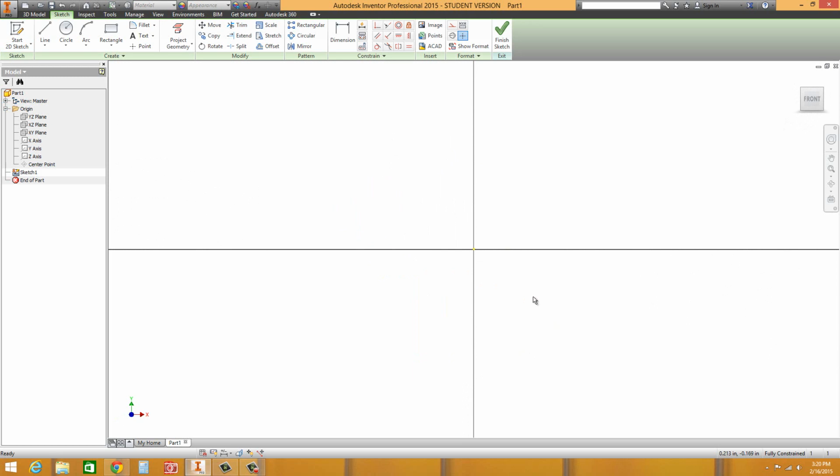Now in the center you have your little origin. Avoid accidentally deleting that if you can. Sometimes people click and drag over it and hit the delete key and then that's gone. You can reinsert it, it's just that it's easier if you just don't fiddle with it. Let that be your origin. That's your 0 marker in space, your 0 for X, Y, and Z in this case because of the plane we're drawing on.